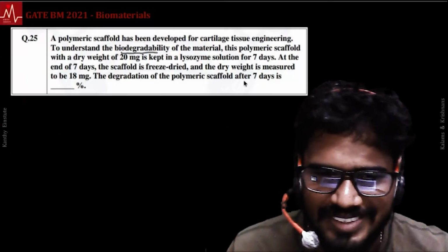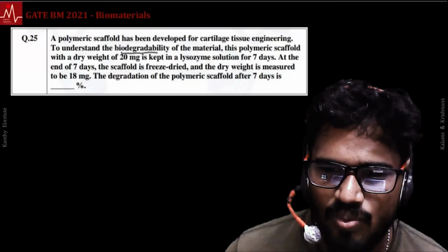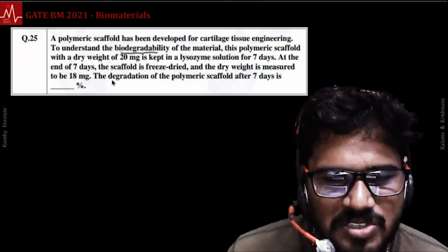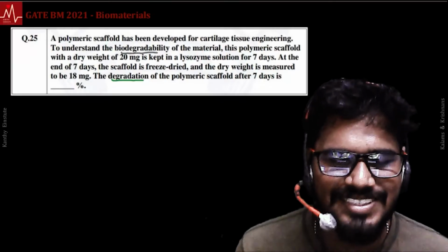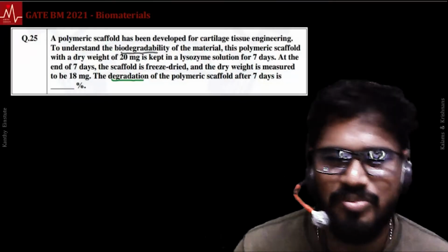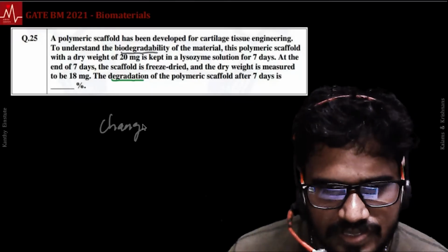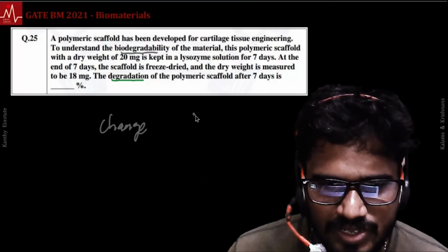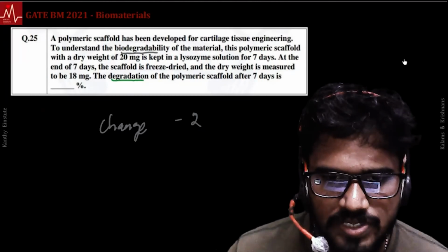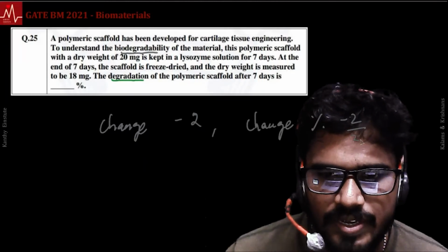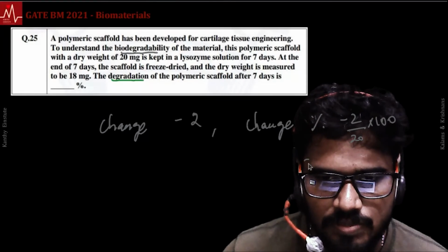The degradation is the extent of change, and specifically the extent of reduction. What is important here is degradation. They are not asking you the change in weight of the polymeric scaffold. They are asking what is the degradation, that is, what is the decrease in the amount of polymeric scaffold. By that, the change is 20 minus 18 by 20, that is 2 by 20. The change in percentage is minus 2 by 20 into 100, which is minus 10%. But they are not asking you for the change percent.